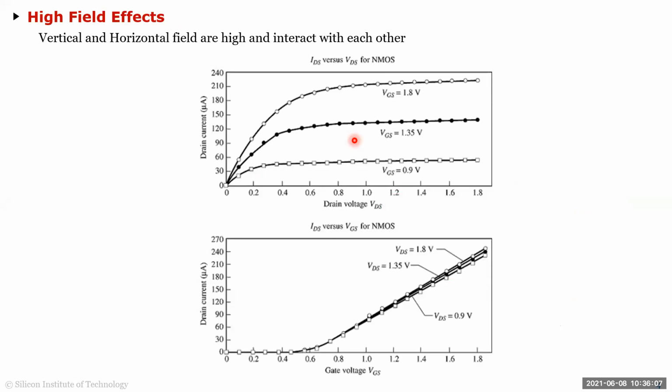Okay. So what has resulted is, as I said, the currents have been decreasing for the same given VGS voltage. If you look at the drain current versus VGS, you remember it is a square law, right? So it kind of does this square law. But once you reach these high field effects, it's actually more linear than square law. You saw that when we did the root ID plot: at the higher end, the root ID plot kind of flattened out, which means the square of that is more linear in nature, right?